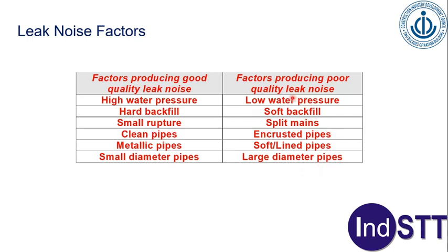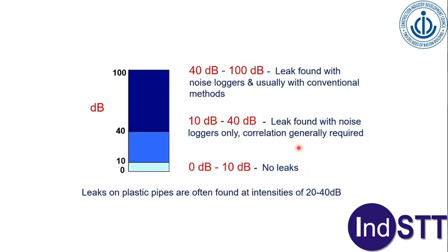So once we are talking about the noise correlators, or listening to the noise of the pipe, all these factors need to be considered. It's not that you will be able to listen to a good quality leak noise in all the cases. It depends on these factors.